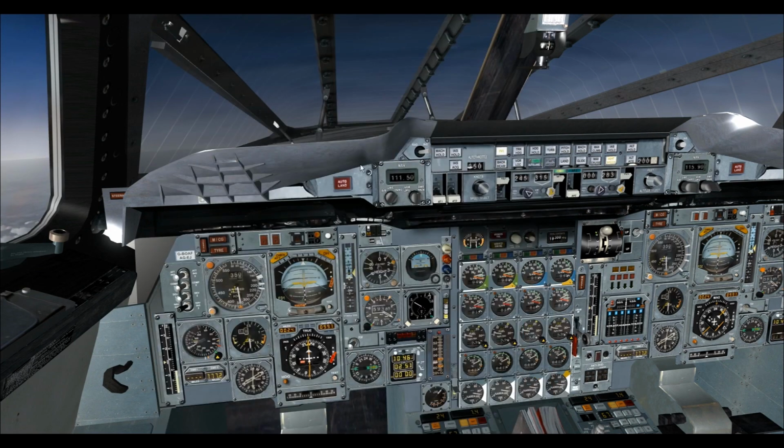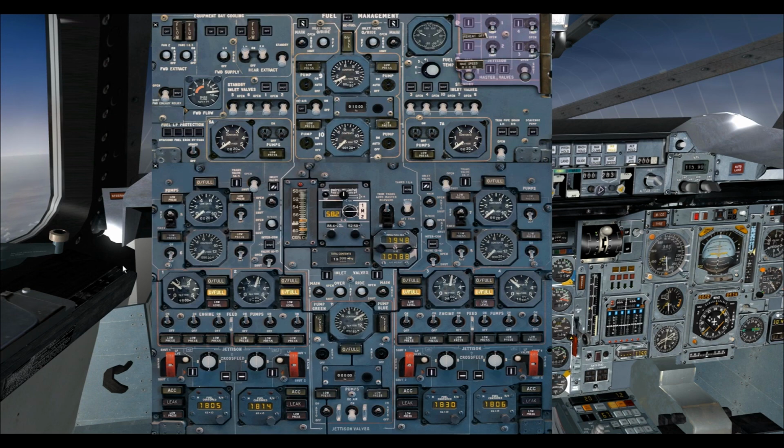With regard to the number for the load limit controller in tanks 9 and 10, there is a landing value that was calculated, but I do not have access to how that is done. I've arbitrarily picked 1,000 kilos. You can set it at 1,000 kilos or maybe a little bit higher, or you can just leave it at 0 and put all the fuel into tanks 5 and 7, and that'll still give you a very good result.